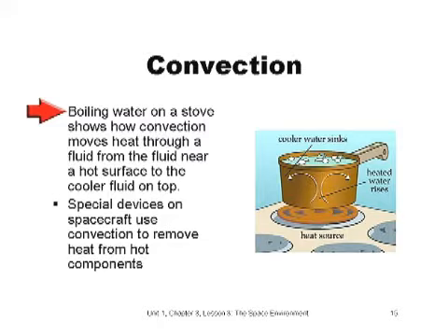A spacecraft has special equipment to use convection to take heat away from components that get too hot. Since there aren't many molecules in space, convection doesn't remove heat from the spacecraft. In a spacecraft, we must bring our own molecules if we want to use convection to cool electronic equipment and people. In this case, we bring air and move it around in the space shuttle using fans.